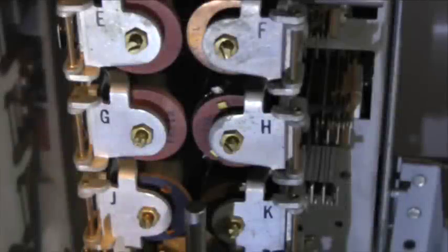2 other relays in the connector are slow operating relays. These are the F relay and the K relay. A slow operating relay is designed to not operate until some other pertinent circuit event has had adequate time to ensure its completion, or to prevent relay chatter during alternating current applications not meant to operate the relay, or to prevent operation from inadvertent momentary direct currents that are meant to be sustained in order to operate the relay.